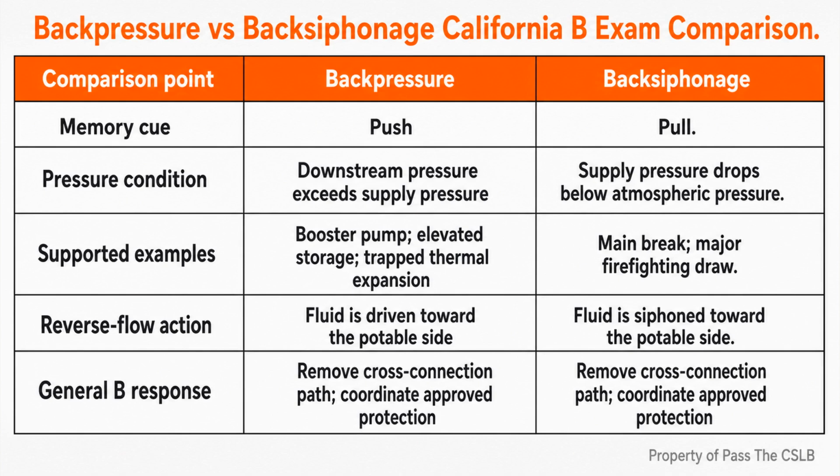The initial test described in the California Plumbing Code uses pressure to reveal a hidden connection. The potable water system is activated and pressurized. The alternate water system is shut down, fully depressurized, and drained. The non-potable fixtures and outlets are then observed. If water appears where the alternate system should be empty, the systems are not isolated as intended.